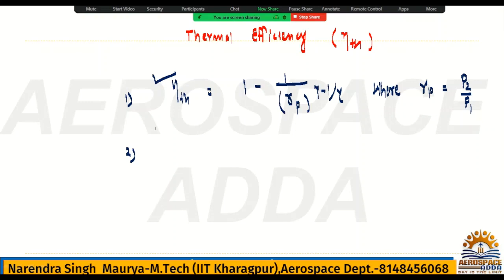That also needs to be remembered. Why is the propulsive efficiency considered the external efficiency? Because there you had seen the thrust power output divided by the propulsive power, yes or no? So that was related directly to the output of the engine. But the thermal efficiency is not related to the output power. It is related to the energy conversion going on in the combustion chamber. Hence it is called internal efficiency.